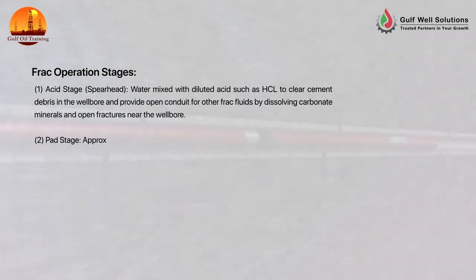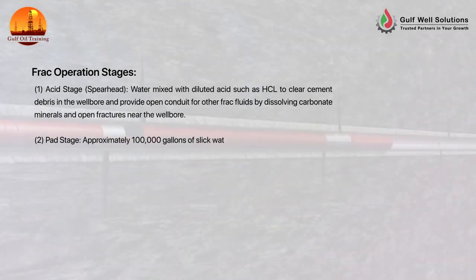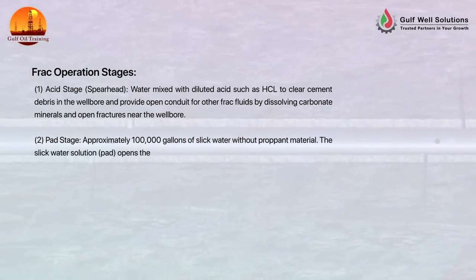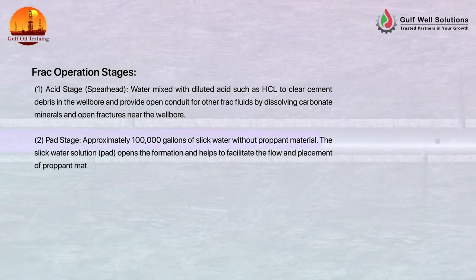2. Pad stage: approximately 100,000 gallons of slick water without proppant material. The slick water solution, the pad, opens the formation and helps to facilitate the flow and placement of proppant material.